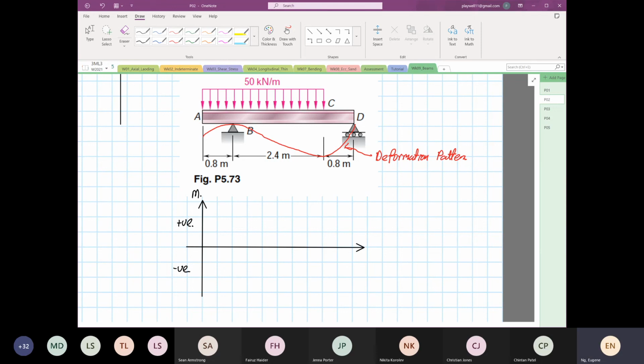The beam is going clockwise or anti-clockwise. There is nothing to do with clockwise or anti-clockwise relating deformation to bending moment. So what does positive bending actually mean? Positive means the beam is bending downwards, and negative means it's bending upward. Yes, you are partly right.